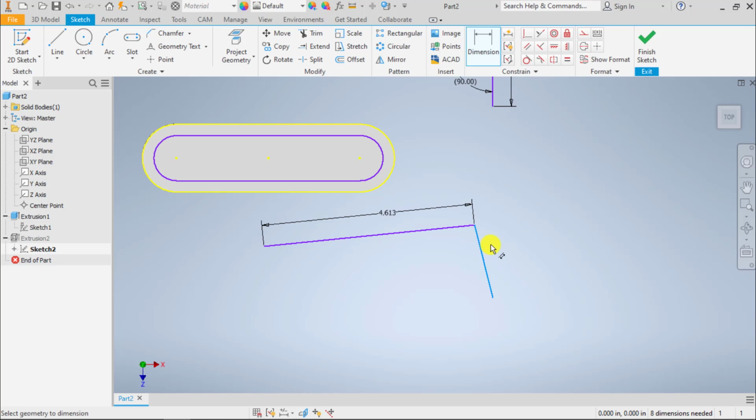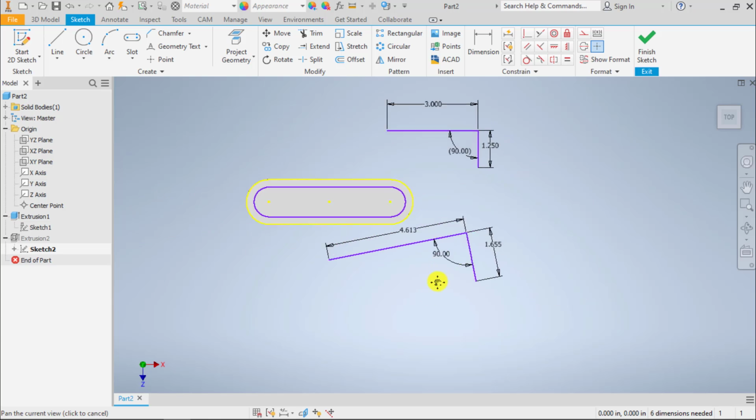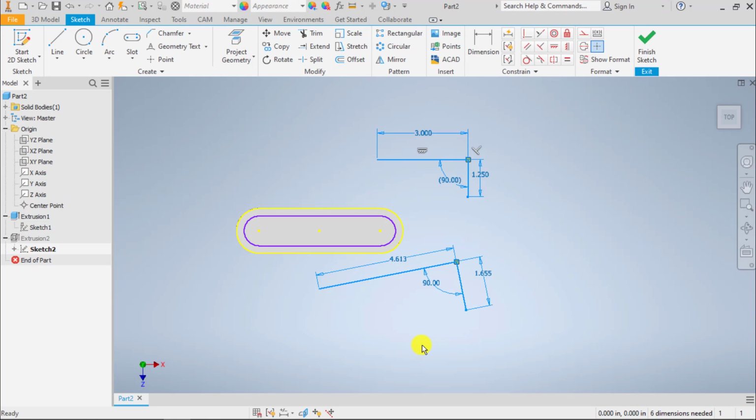I'm also able to do the same thing on this line. I can now derive the angle with a dimension. I can set this to be 90. Now notice that it did not set the angle of this to be horizontal. But if I rotate this, it maintains the relationship between those two of 90. So that's kind of linear dimensions, aligned dimensions, angle dimensions.